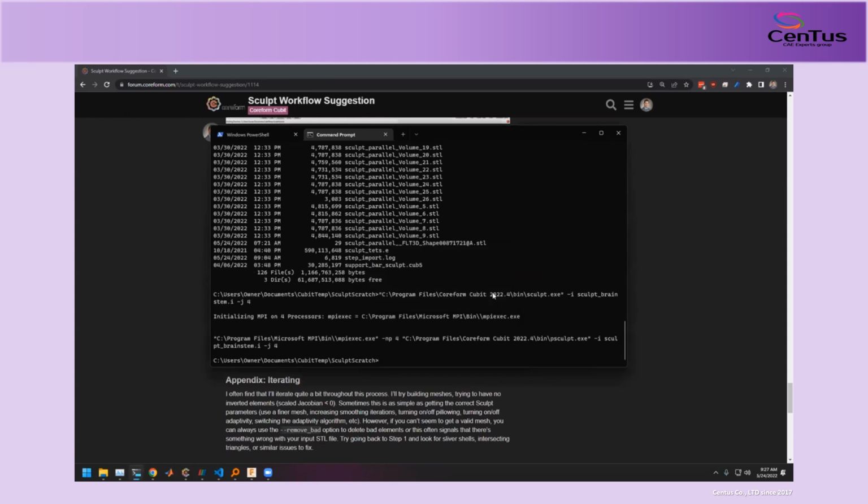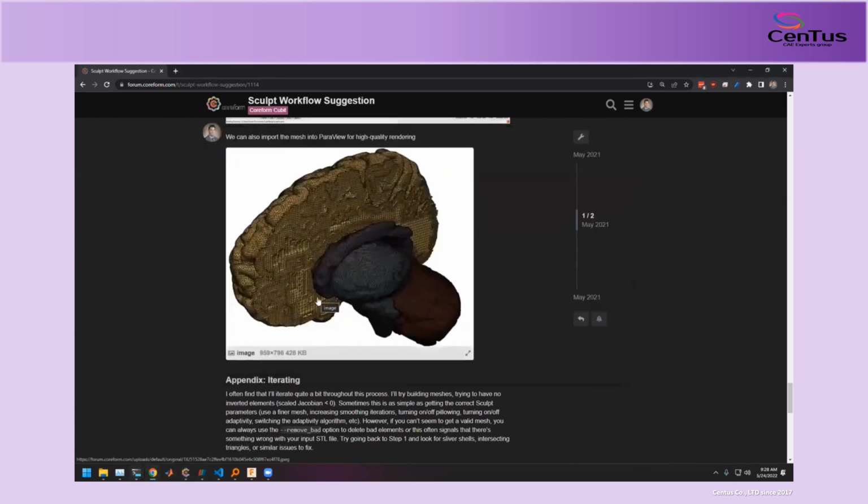Great, thanks. So Greg, the full brain model, is that a conforming mesh that you have with multiple parts? The resulting mesh that comes out, I don't believe the resulting mesh is conforming, just based on how I set up my script to run. I use different sizes for the different regions because the individual organs themselves are not connected.